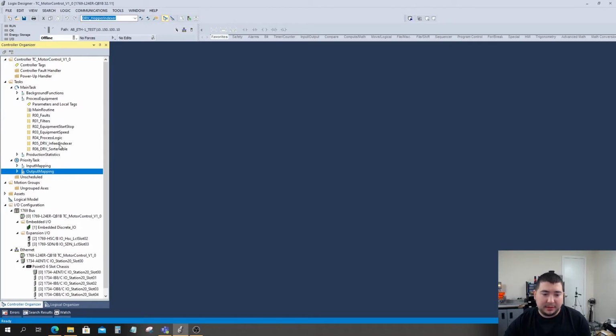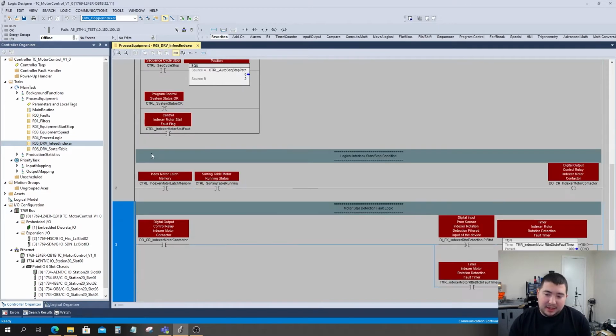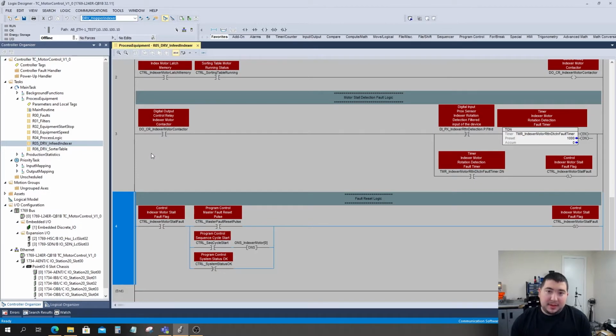The first part about motor control, as far as speed, is we need to be able to scale our speed. So we talked about the scaling in the card, but obviously that's not the scaling of the real world. By keeping it in the program, it's easier to manipulate. So if the gearbox changes, or if we change motors to a different ratio, and they have a different maximum RPM at 12 volts, then we'll be able to just easily manipulate parameters in the program, and then the motor itself will not change. So a very common scaling technique would be a linear relationship scaling.